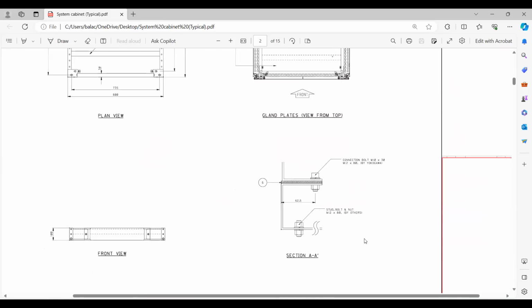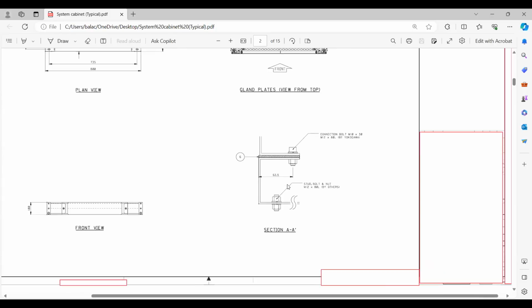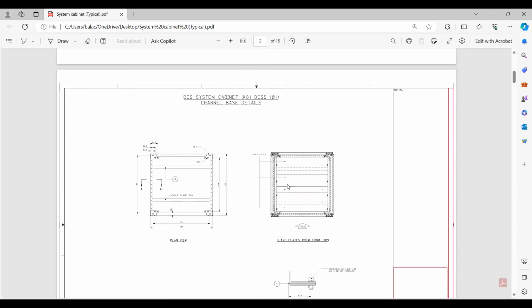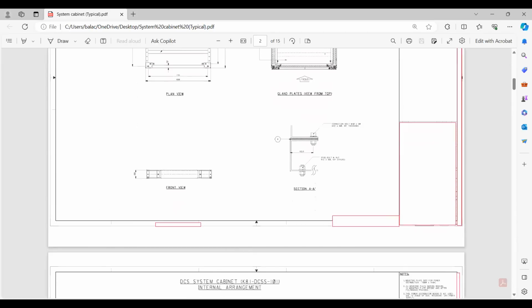And what is the sixth item? Item 6 also I want to give you. This is actually the insulator. If you remember, between the panel and the base plate, the channel base, there is a hylam sheet or something like that. We highlighted, right? Some insulator in the specification. Yes, that is the thing. This one, 5 mm, it can be a bakelite also. This is the insulator, friends, right? Okay. I hope this is also clear, right? Yes. So no special notes here.